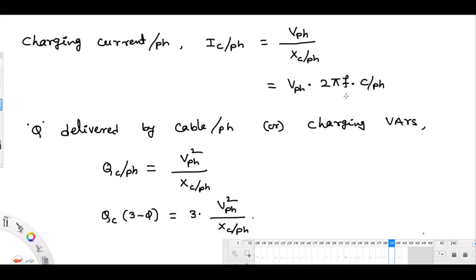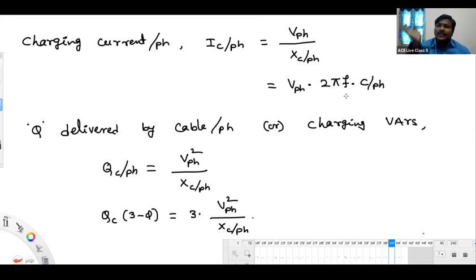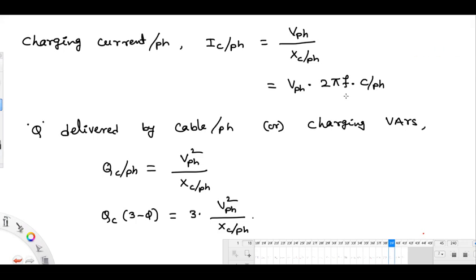But for that input reactive power supplied by the source in the converter, which element is responsible? You are showing one DC voltage source at the end, a charged capacitor you are keeping. There is some energy stored in that. Because of that voltage, you are converting it to AC. You are maintaining a potential gap between the converter output voltage and system voltage. Because of that voltage gap, there is a reactive power circulation.